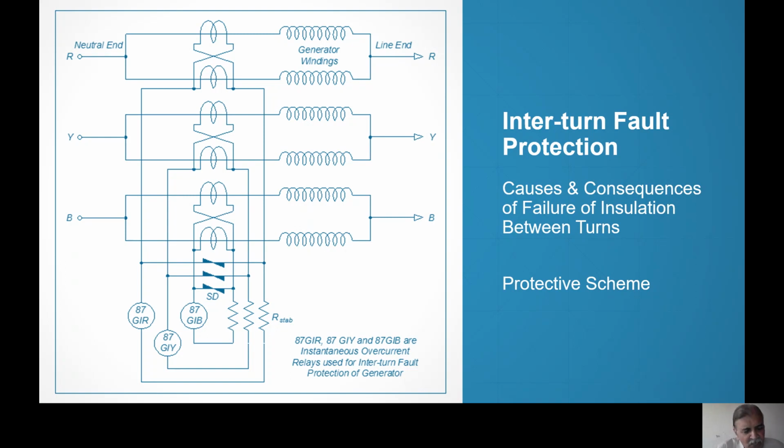87 is the number for differential protection. It is an internationally known number. Anybody in the world, if you say 87, will understand you are talking of differential protection. And once again, for external fault, there is a possibility of maloperation, possibility of instability. So our setting and the calculation of our setting is similar. Everything is similar. This is differential protection.